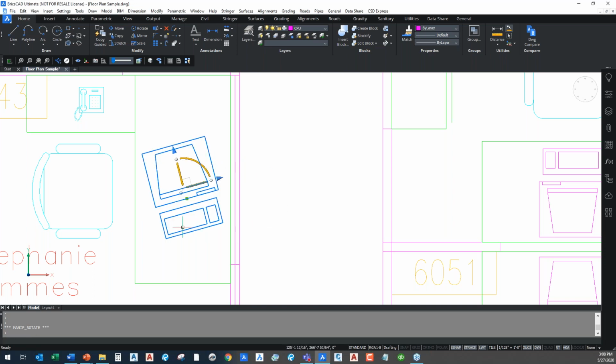Now, the other thing that's really nice about this, you'll see that at the end of the arcs here, I have these two little gray circles. I can also do included angle rotation. Instead of full angle rotation around a full 360, I can do it on a 180 plane. So I can go down or up 45, down 45 off of that central point, right? And I can do it on either side just by clicking this gray circle, and I can spin my object.